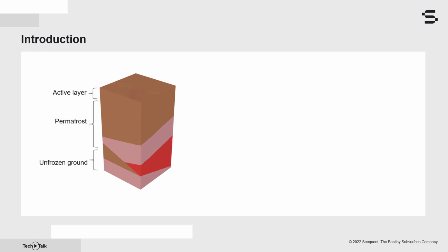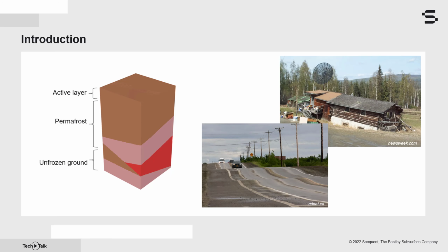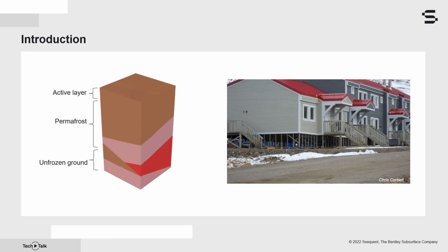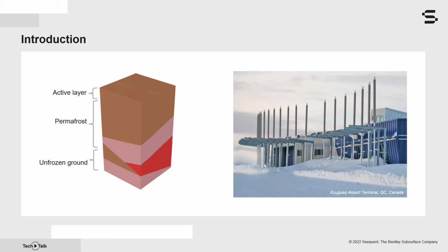Constructing man-made structures on permafrost, including buildings and embankments, is challenging. Heat transfer from a building can melt permafrost, causing subsidence of the ground surface, among other environmental challenges. Thus, great care must be taken when building in Arctic regions where permafrost is present. In some cases, buildings are constructed on piles to minimize their influence on the underlying thermal regime. However, this type of construction is not always practical. Buildings constructed as slab-on-grade must employ other techniques to minimize thermal impacts.